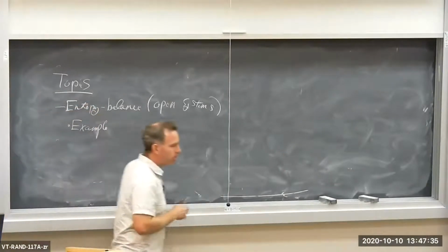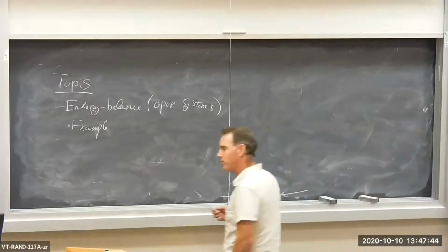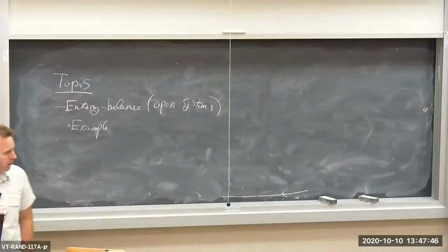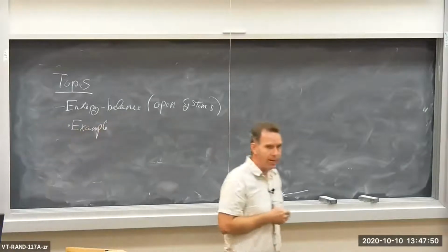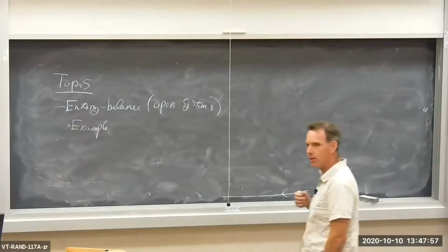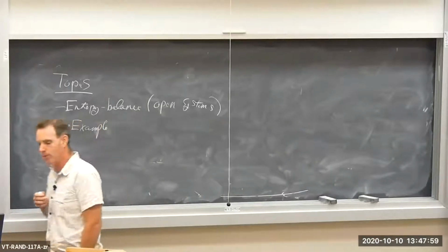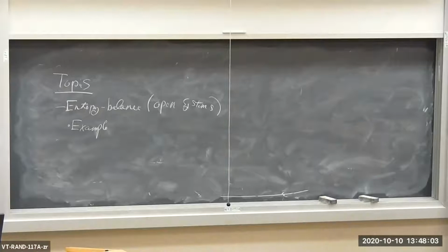How entropy flows in and out of open systems, how entropy is generated in open system devices. So we're going to move on to open system application of the energy balance today. And as you might vaguely recall, we have a process or a machine or a function for transforming closed system conservation relationships into open system conservation relationships, the Reynolds transport theorem.